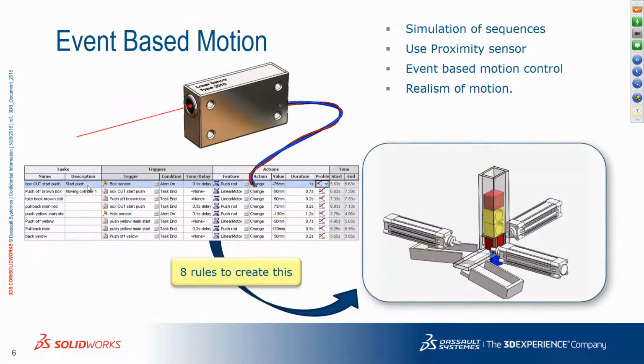And so here it is. One is what you saw now, more of kinematic simulation. But saying that, I would also like to highlight there is something called event based motion in this, or it is an extended module of motion, wherein you can actually create motors which respond to certain events. So as you can see here, the particular red box is not having a hole, and there is a yellow box which is actually having a hole. So we can have a sensor down there which will sense whether the part is having a hole or not, and we can do the sorting.